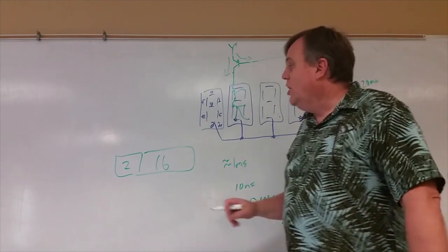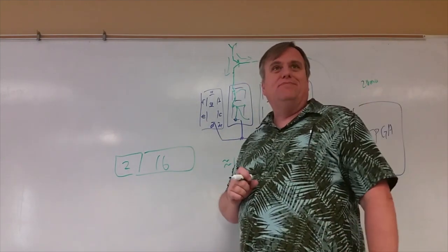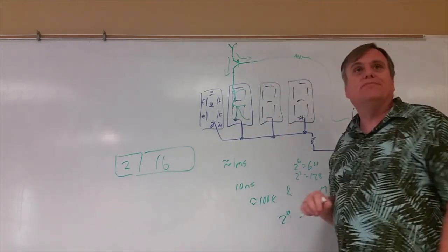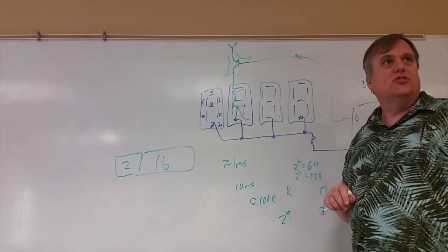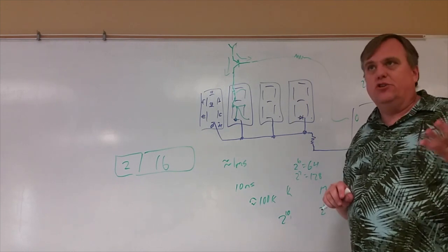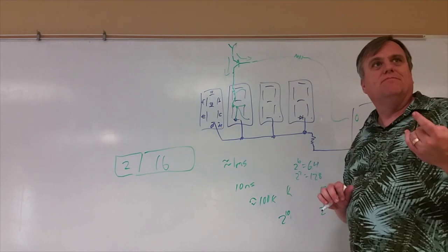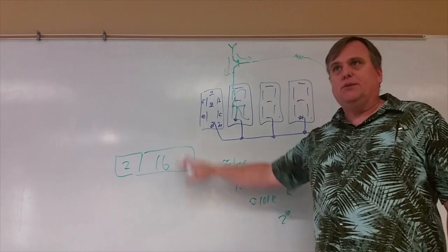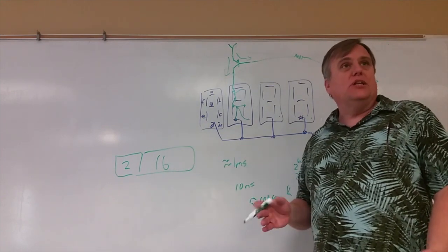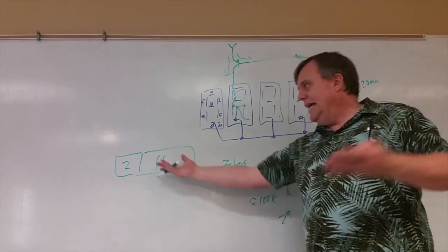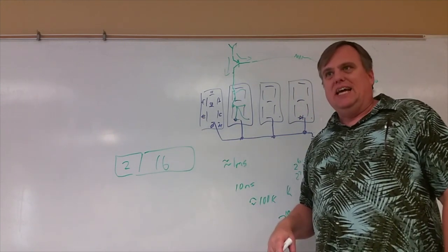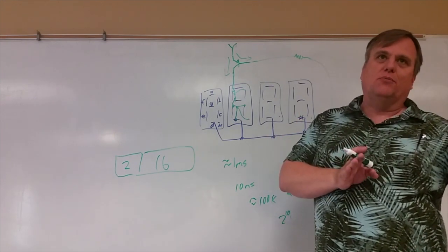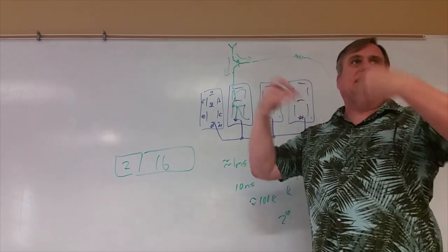All right. So all I need then is an 18-bit counter, and I'll output the last 2 bits, and that'll become the selector. That make sense? So that's what they do. You just build a counter. Every clock cycle just adds 1 and writes it back to that number. It's a pretty simple one. It's an 18-bit flip-flop, and there's an adder that takes 18 bits from the state, adds 1 to it, and gets the next state.